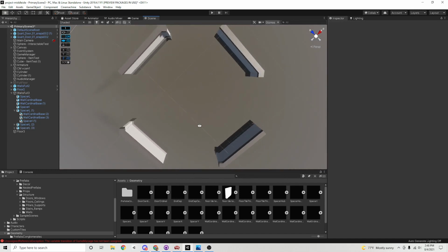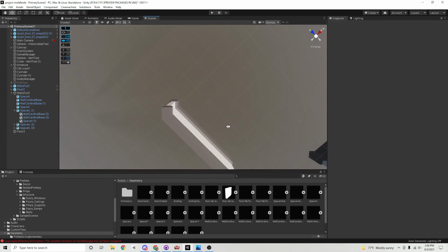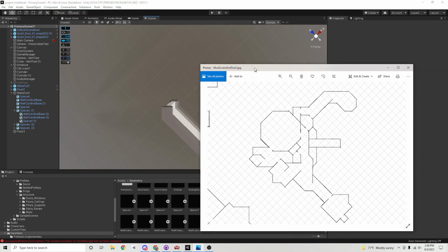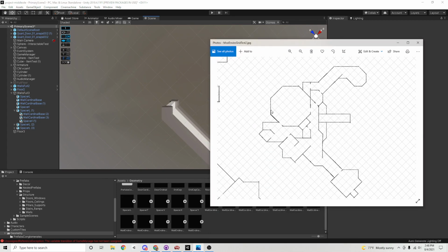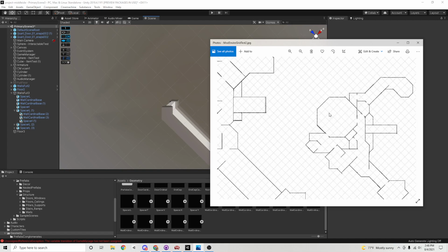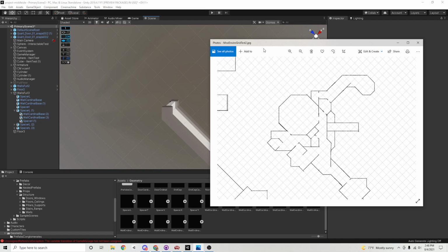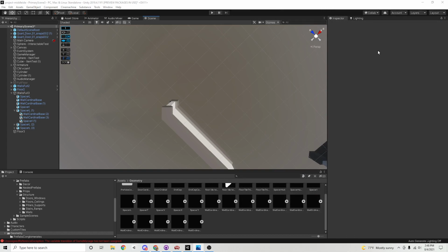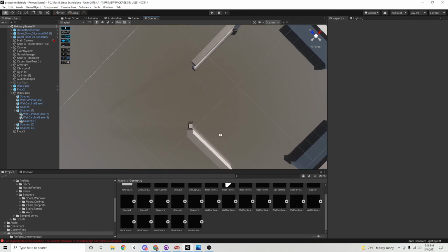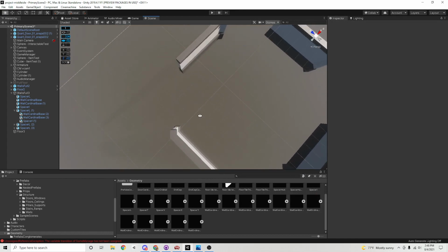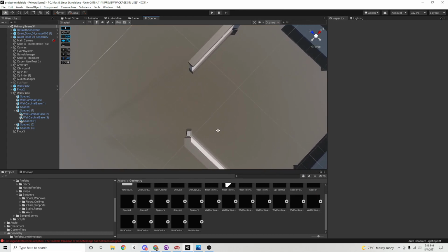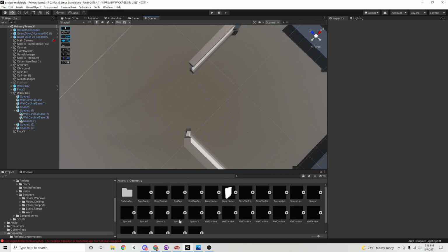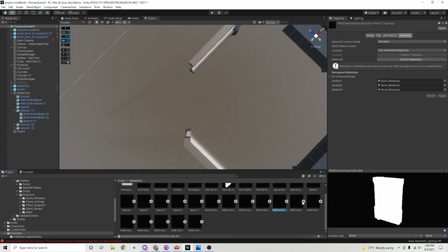And now I'm going to introduce you to the ordinal pieces. The ordinal pieces make up the straight, or the straight up and down, on our diagonal grid here. And they are bigger because they have to take up a full diagonal rather than a square side. This is why you can't swap cardinal and ordinal. One is one, the other is the other. You never want to be rotating a wall piece on a 45 degree. You always want it rotating on a 90 degree.